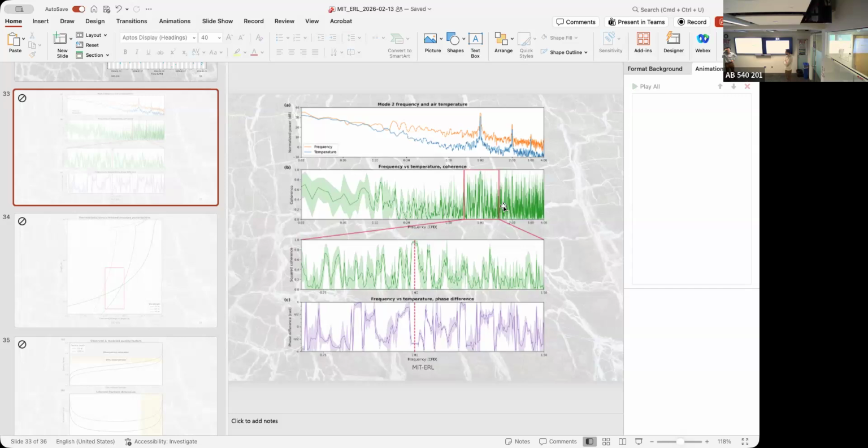It's pretty hot. And also, one thing that I think promoted the thermoelastic stress is, first, it's a desert, so there's a very strong diurnal temperature variation. And also the surface is dark gray, so that absorbs radiation really well. So what we're showing here is the air temperature, but it's not the surface temperature. And we expect the surface temperature variation to be much more extreme than the air temperature.